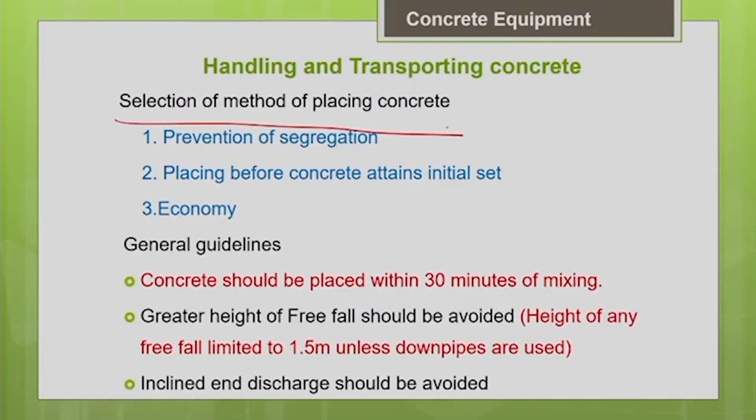So, how will you select the method for placing the concrete? Once the concrete is prepared, our main objective is to transport it to the place of casting as early as possible, without much loss of time. As you know, once you add water to the cement, the cement starts setting because of the hydration reactions. So, before the cement attains its initial set, we need to transport the concrete as early as possible to the casting place.